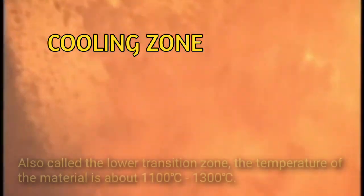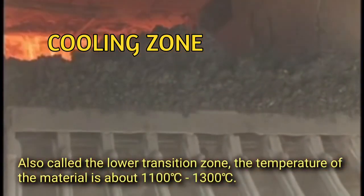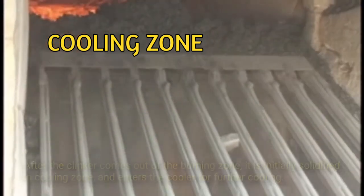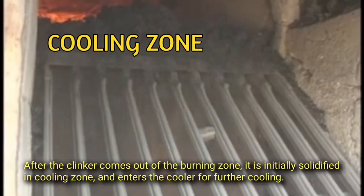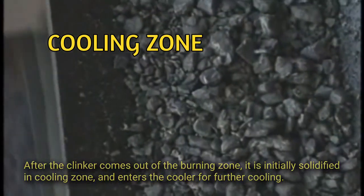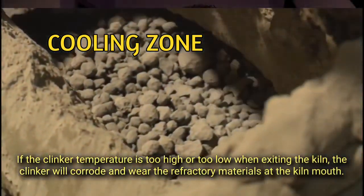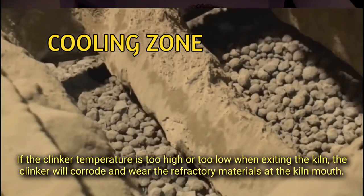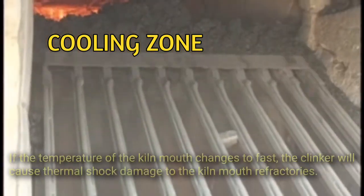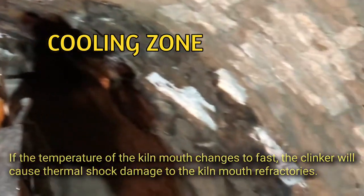Cooling zone, also called the lower transition zone. The temperature of the material is about 1100 degrees Celsius to 1300 degrees Celsius. After the clinker comes out of the burning zone, it is initially solidified in the cooling zone and enters the cooler for further cooling. If the clinker temperature is too high or too low when exiting the kiln, the clinker will corrode and wear the refractory material at the kiln mouth. If the temperature of the kiln mouth changes too fast, the clinker will cause thermal shock damage to the kiln mouth refractories.